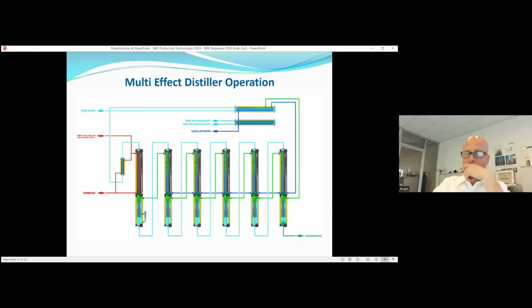Then, when we have created the dry pure steam from the last column, we have the condenser and the other exchanger, the cooler, in order to condense the pure steam into WFI. Typically, this machine works with WFI outlet at 99 degrees.